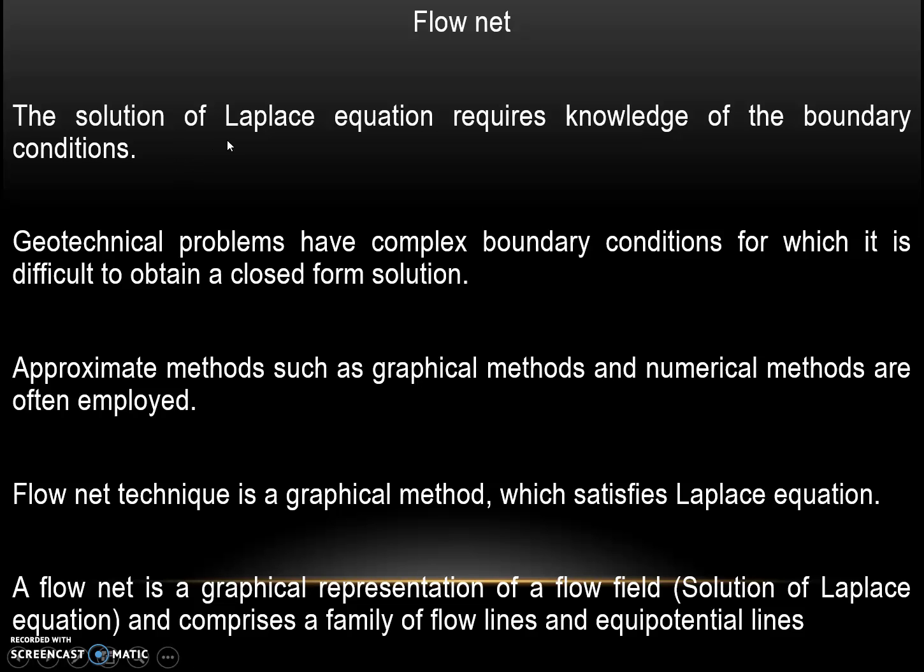Now we'll go through Flownet. The solution of Laplace equation requires knowledge of the boundary conditions. Geotechnical problems have complex boundary conditions for which it is difficult to obtain a closed form solution. Approximate methods like graphical methods and numerical methods are often used. Flownet technique is a graphical method which satisfies Laplace equation.